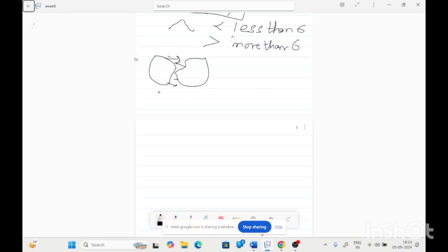So in the recrystallization process, the strain free grains form and they start growing, and that strain free nucleus starts to consume the rest of the material, which will get strain free.